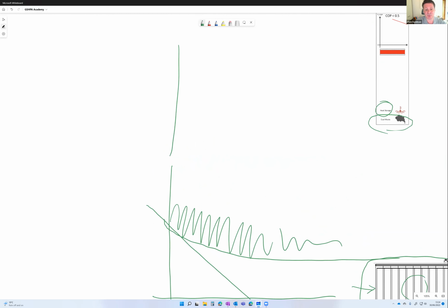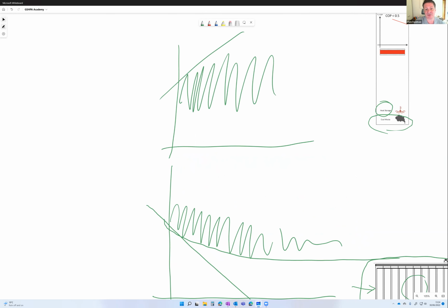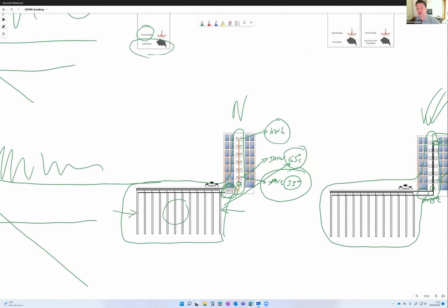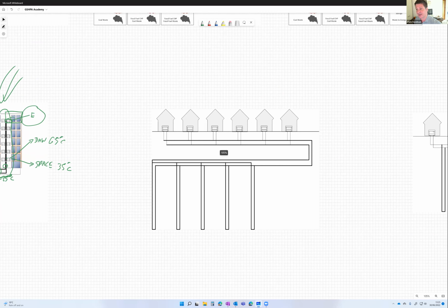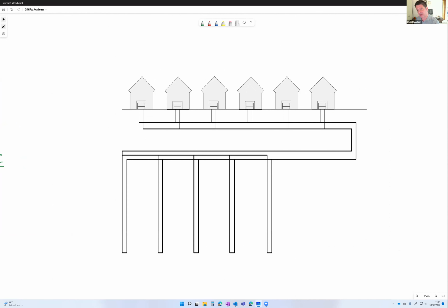Heating and cooling systems will be slightly different. They'll do this winter and summer. And again, you don't want that just going up and not going down. You want these tending to a limit, and you want that limit to be within the sweet spot for your heat pump performance. So, a very quick overview. If it is getting colder and colder, it's not a big enough ground loop, not a well-designed ground loop, simple as that. We've got more sessions on that in the webinar series, and if you want to get into real good detail on it, stream 1, the training that I mentioned for consultant engineers, we get into it in quite a bit of detail there.